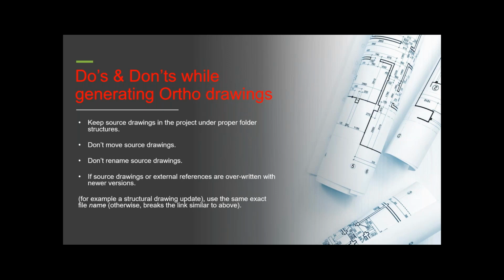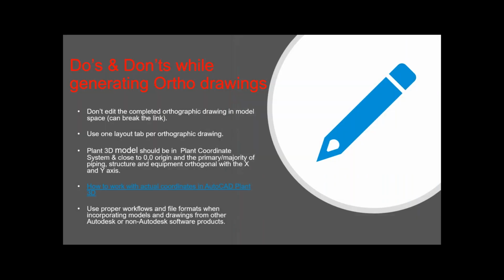So now let's go a little bit more into the do's and don'ts when you are editing your ortho drawings. Don't edit the completed orthographic drawing in model space. For each ortho drawing, you can do it on the layout and make modifications. Say maybe you want to add some annotations, some additional insulation, or some symbols, or make modifications to the ortho BOM. All those things you can do in your paper space, but don't attempt to modify your ortho drawing in model space. Again, this can break the link.